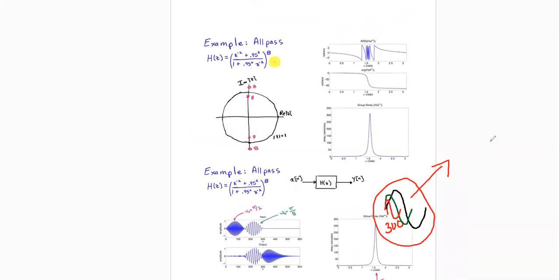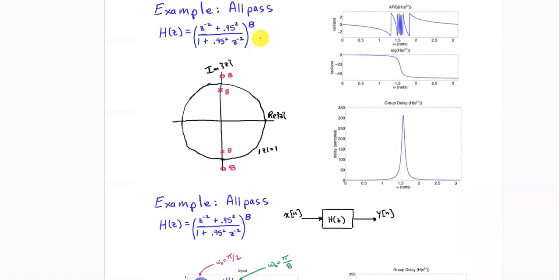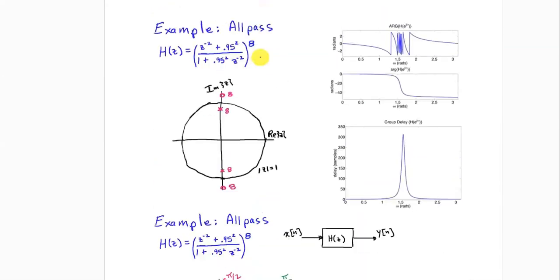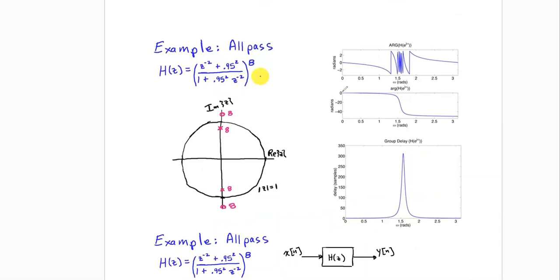Okay. So I would like to represent this with another example with the group delay concept. It is a very interesting one. So this is an all-pass filter. Maybe we need to give one example of the all-pass filter afterwards. In the all-pass filter, they will pass everything. So just concentrate on the representation of this. Let's say this is an all-pass filter. For all-pass filter, this is your phase response, and this phase response is non-linear.